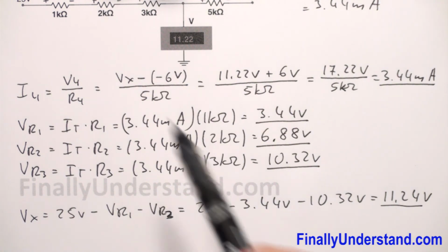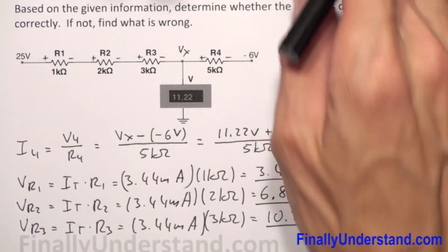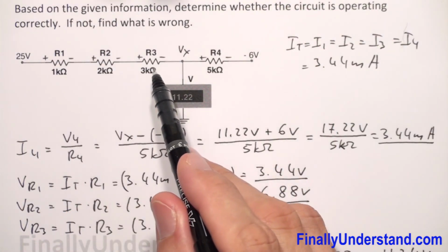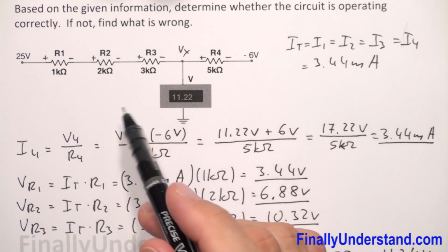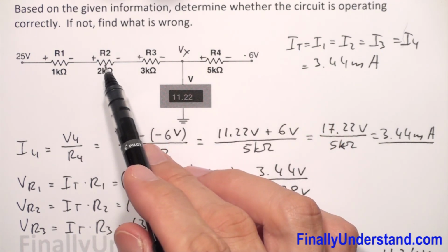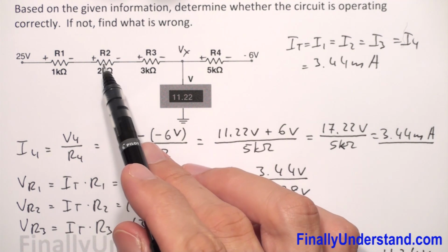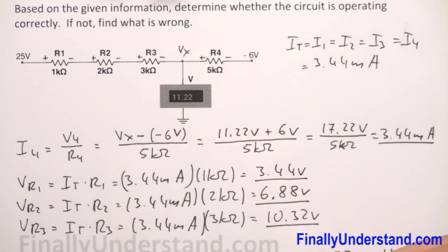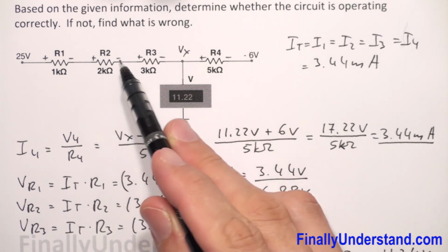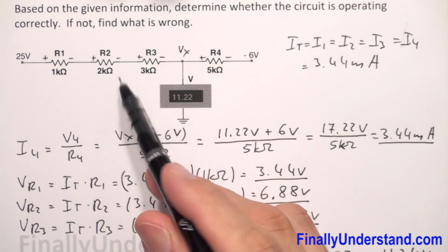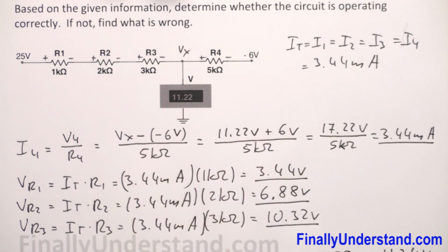So it means that resistor R1 and resistor R3 are functioning properly, and I've got the problem with resistor R2. R2 has an internal short. So it means that this resistor has to be replaced. And this is simply the solution to my problem.